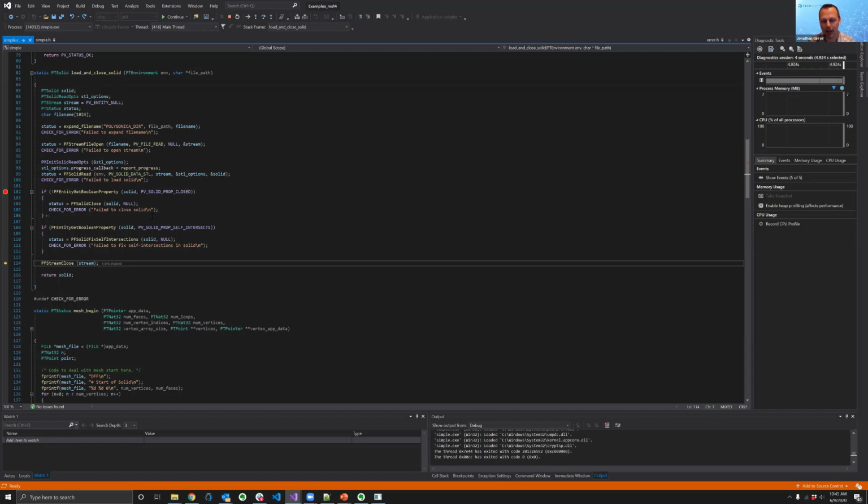And you can say it's either left-handed or right-handed oriented, but sometimes they go in reversed ways. So you might have a right-handed triangle next to a left-handed triangle in which the vertices are indexed differently. And so again, another one of these fix functions allows you to fix the orientation of your vertices. You can fix non-manifold edges. You can remove noise shells. So it's a lot of different functionality to prepare your data for downstream workflows.